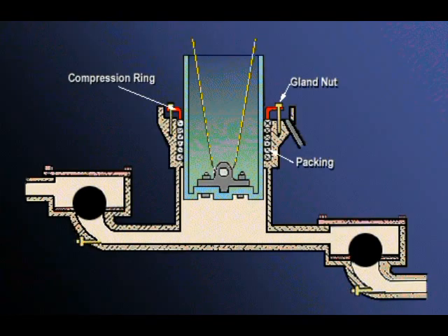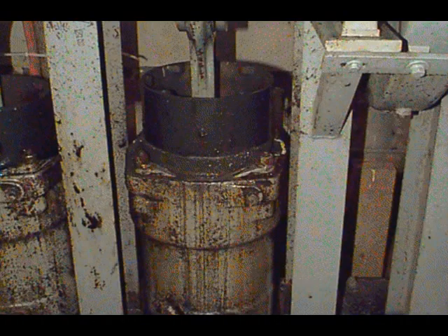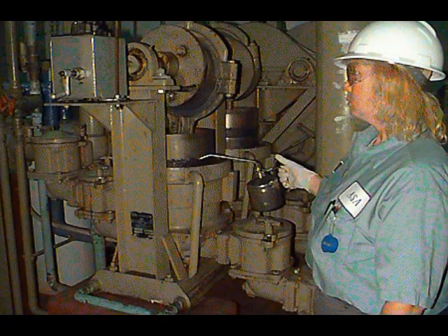The packing in the plunger pump is similar to the packing in the centrifugal pump, except that the lantern ring and seal water are not usually provided. In the plunger pump, a small amount of leakage is usually permitted so that any abrasive particles that get between the packing and the plunger eventually work their way to the top of the stuffing box where they can be flushed away. When the packing is new, it is good to loosen the packing slightly after the pump is in operation. Add oil and retighten the gland bolts. Do this 3 or 4 times at 15-minute intervals to set the packing properly.